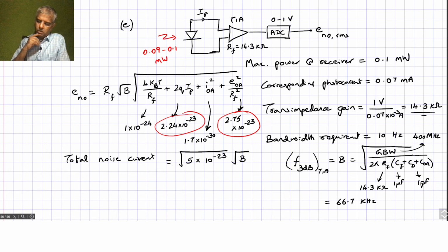If you, for example, go to 1 millifarad, then you can actually get to a much smaller value, but to get to 1 millifarad you need a fairly bulky capacitor. So, it is not compatible typically with a PCB, okay. So, that is the constraint that we see. So, because of this, this is actually the total noise current that we have looked at,